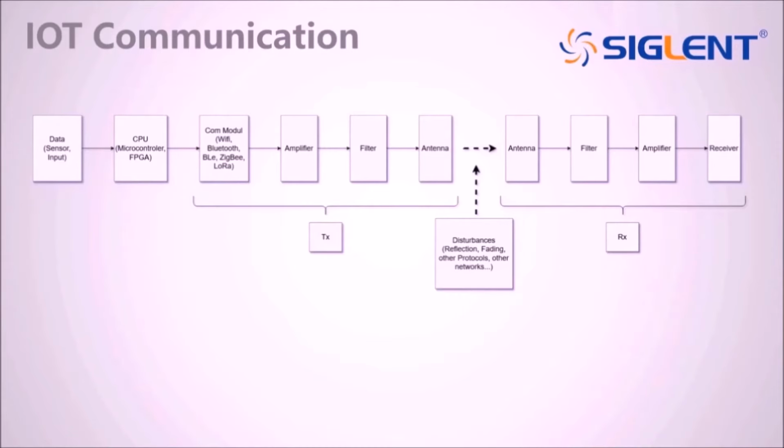If you are designing a system that is planned to be manufactured in small numbers for a specific application, then you will probably use a finished module that has the entire interface, including antenna, already integrated on one circuit board. Or you're the one who designs such a module for integration. Then you have to keep an eye on the entire communication chain, from the data source up to the antenna. There are also many partly integrated solutions which are often used. For example, a ready-made Bluetooth module for something like a smartwatch. Such a module is mostly integrated, but has to be used with an external antenna to get out of the metal housing.